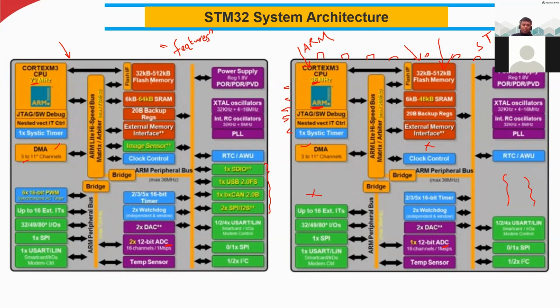So we have the memories and we have the DMA. Sometimes we read directly from the memory to this direct memory access block, and we do not need to use the CPU resource. Sometimes we need to transfer data back and forth all the time during the operation, so we cannot really use the CPU to take the data.